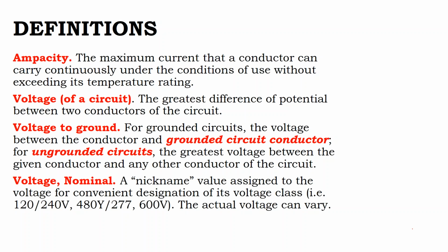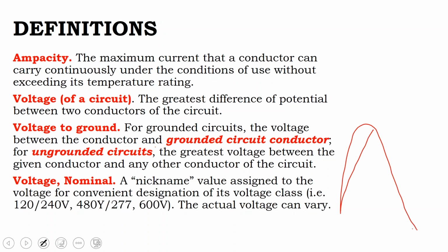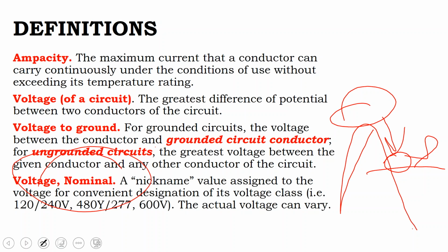A solar inverter, you say, oh, well, it synchronizes up to the grid. Well, what does that actually mean? That solar inverter is operating at a higher voltage potential than the grid. The solar inverter is trying to be at the top of the mountain. Your grid might be halfway down the mountain, so that it can push its electricity out onto the grid. You push electricity from a higher voltage down to a lower voltage. And so we might say, okay, the grid is at 240 volts, or our electric service is at 240 volts. So our nominal voltage from our solar inverter is a 240 volt AC inverter. But it might actually be operating at 245 volts to push that electricity out onto the grid.